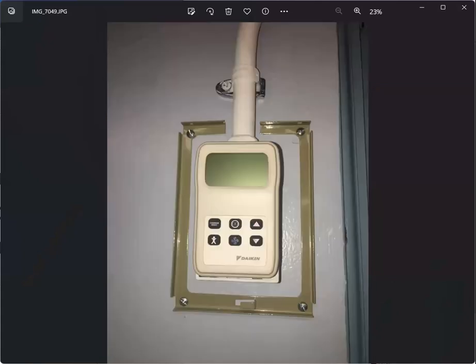This is the thermostat for the room that will control the new ventilating unit or AC unit. At the end of the job, you need to make sure that everything is functional. This is lit, and the contractor should call you for another inspection just to confirm that everything is functional and working well. If not, you could ask for the commissioning report just to certify that everything is working.